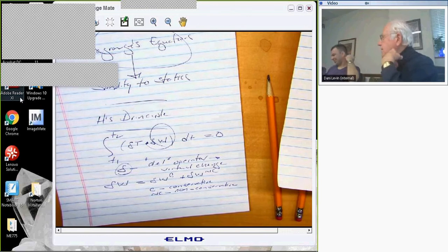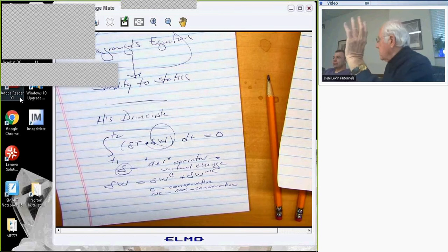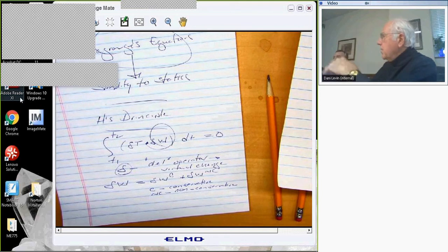Here it is. Okay. The good news for the fluid side is that in aeroelasticity, often the dominant source of damping in systems is actually from the fluid. As the structure deforms, it moves, the fluid forces change as a result of motion of the structure, and part of that fluid force creates an effective damping as far as the structure is concerned. And the usual equations of fluid motion, if we can solve them, which is not easy, will produce a damping which has some rigorous basis. That is, ultimately the damping comes from either the radiation of pressure into the far field or from the viscosity of the fluid or combination thereof. So the good news there is there's a sort of a rigorous theory, if you will, of aerodynamic damping.